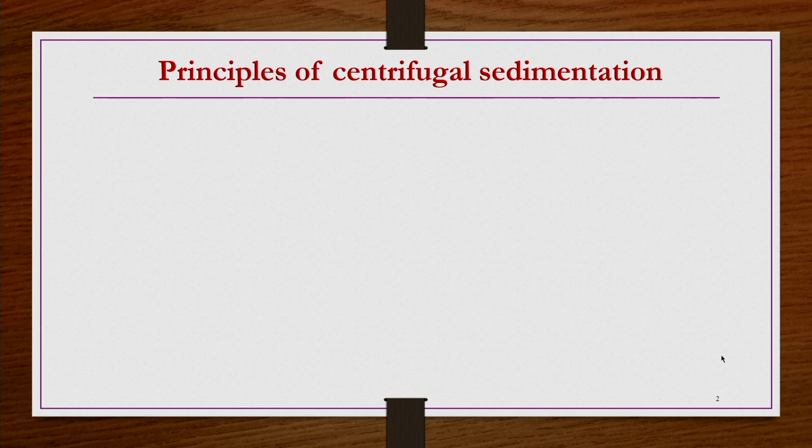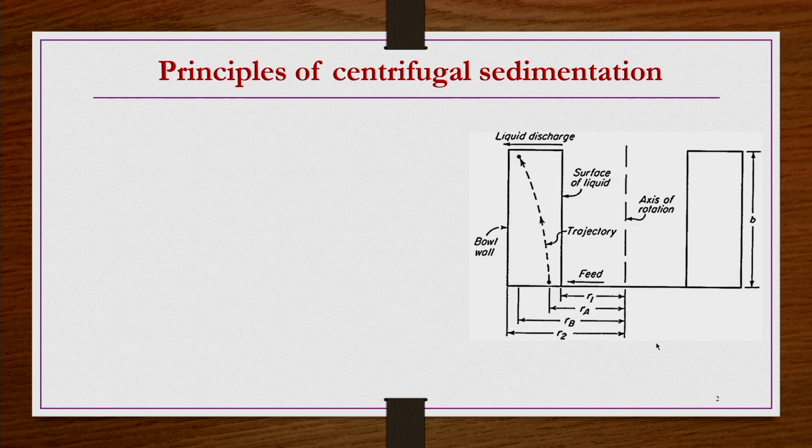Principles of centrifugal sedimentation. Let us assume that you have a solution which is having a few fine particles, and the separation of those particles by sedimentation settling is going to take a long time. Under such conditions, you prefer to go for a kind of centrifugal sedimentation. So, for such solutions, if you are doing a separation by centrifugation, let us assume this schematic is like this.